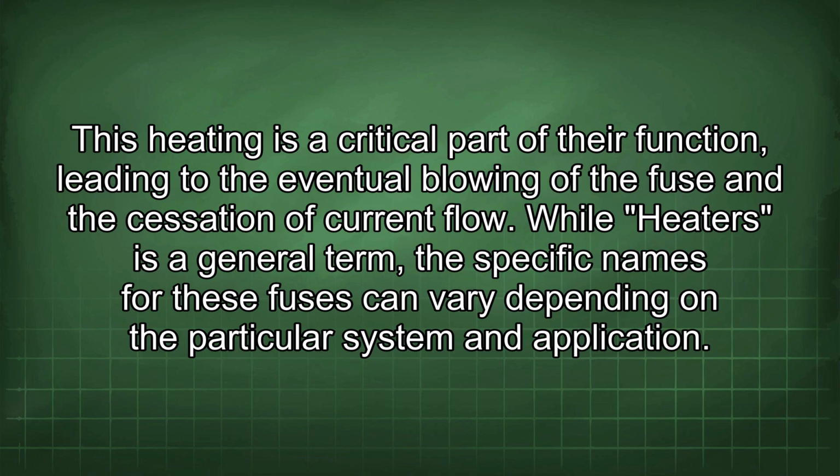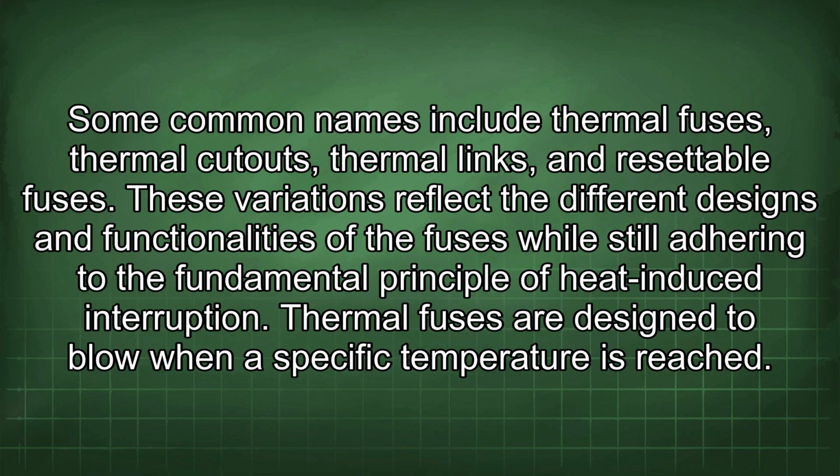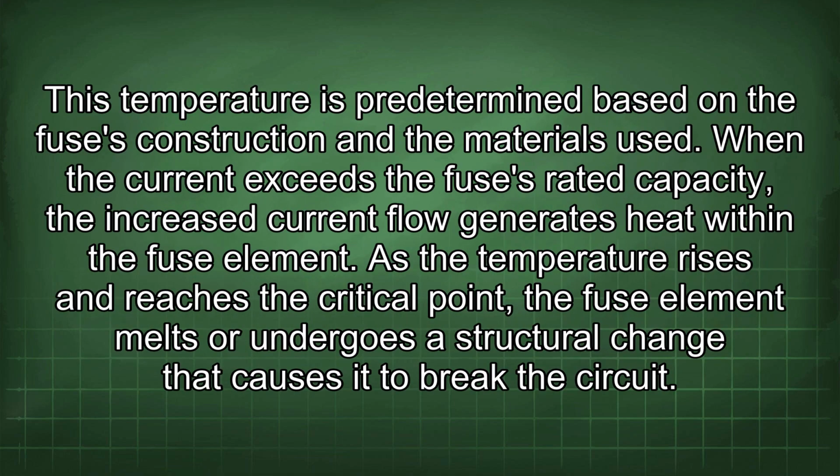of current flow. While heaters is a general term, the specific names for these fuses can vary depending on a particular system and application. Some common names include thermal fuses, thermal cutouts, thermal links, and resettable fuses. These variations reflect the different designs and functionalities of the fuses while still adhering to the fundamental principle of heat-induced interruption. Thermal fuses are designed to blow when a specific temperature is reached. This temperature is predetermined based on the fuse's construction and the materials used.